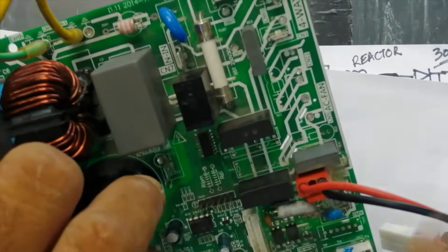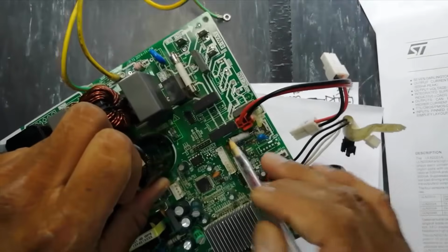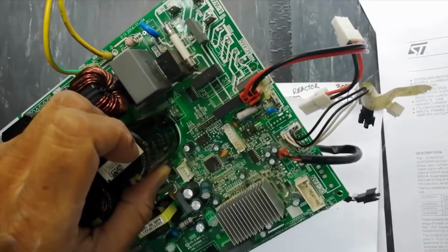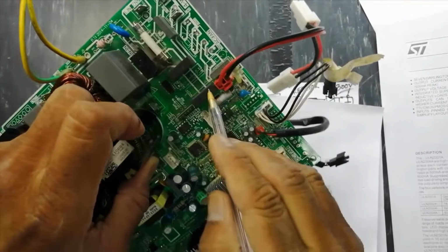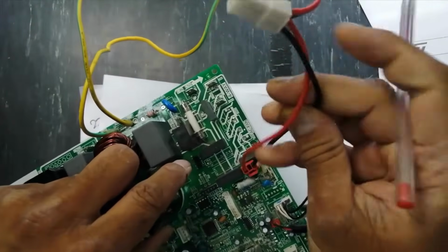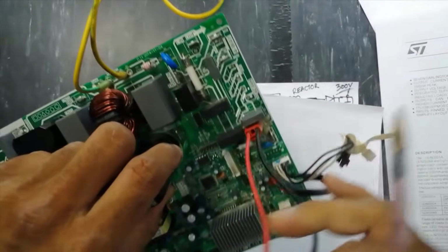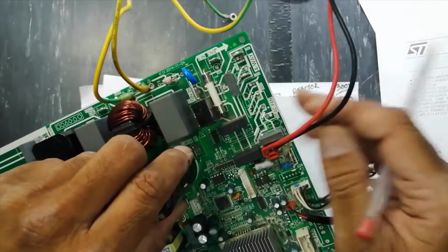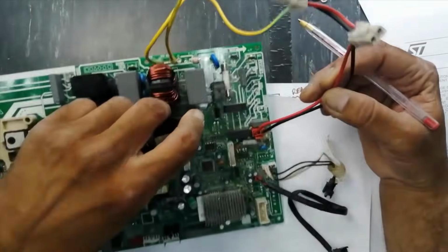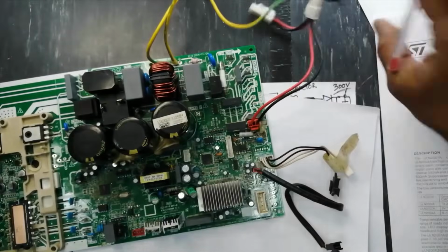And at the same time, if the compressor internal temperature is down, at that time this processor will give command to this relay and it will connect 220 volt to the compressor heater. So it will heat up the compressor to build the proper pressure of the gas. For proper compression, we need 220 volt to connect with the compressor heater. When the temperature is maintained, it will disconnect the command and it will turn off.